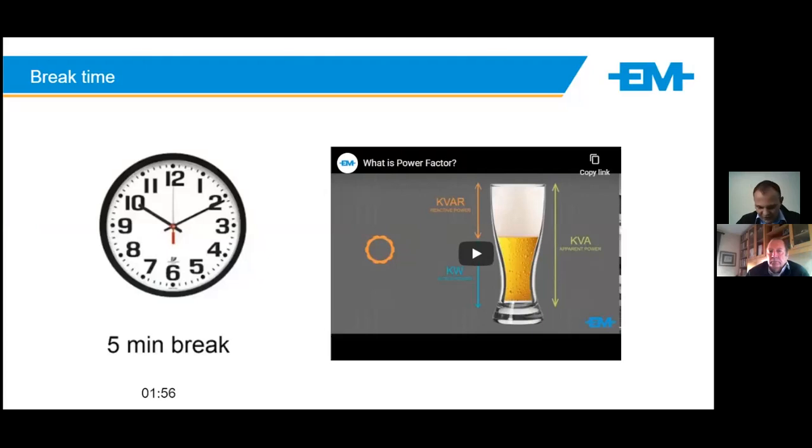So to answer that, the manufacturer will have a scope on that variable speed drive to give you some direction of what size reactor to wire in line with the variable speed drive, and what to put on the output of the variable speed drive. Do you need an additional EMC filter on that unit? All of these obviously add up to the cost.